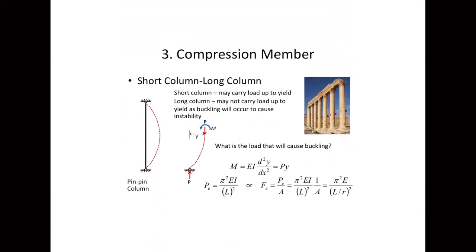Okay. So now you have had this before in your mechanics of materials class, that when your compression member has a considerable length, it loses stability. So the question in that class is, what is the load that causes instability? So again, you can apply the double integration method. You write down the moment equation, which is, you know, when I cut the free body diagram, because the two P's do not coincide now. So to complete this free body diagram, you need to have a moment to help out. So you can write this moment equation, and this becomes the deflection of your compression member.